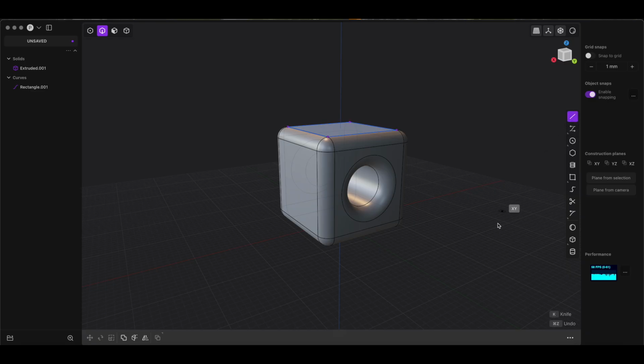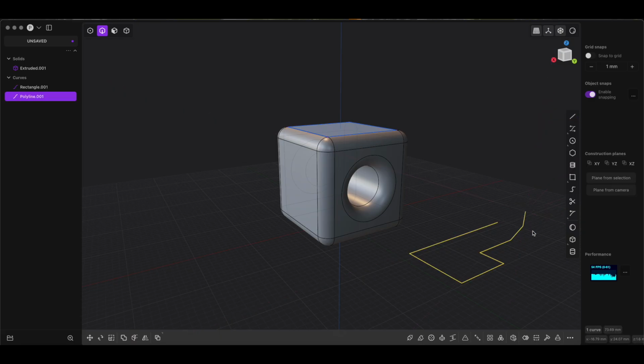If you're going to draw or make any object in the viewport, by left clicking, the tool will continue to be used, it will continue to draw until you hit the right click, which completes the command. In order to delete an object in its entirety, you can select it with the left mouse click and hit backspace. To undo any operation, you can use Command Z or Control Z on Windows.